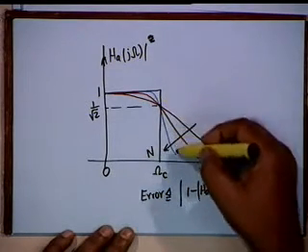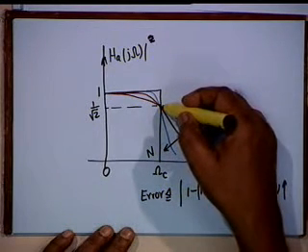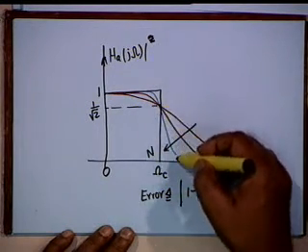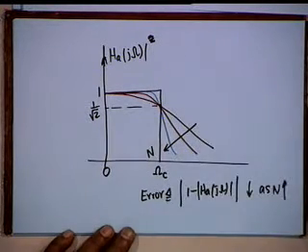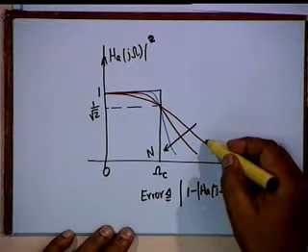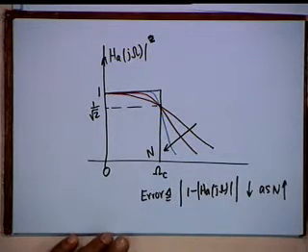You see the blue curve has a higher cutoff slope, and therefore its omega s, the edge of the stop band, starts much earlier than the other curve, for example the brown curve. Okay. So what you do is you determine the order n required for meeting the given specifications, all right.